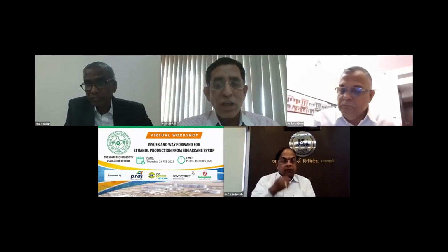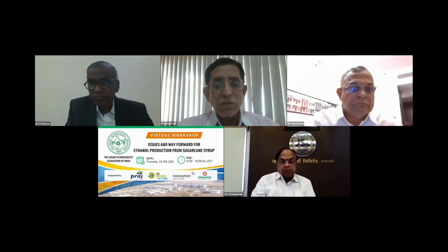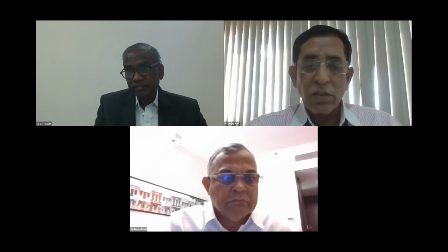Thank you very much. There is one question by Mr. Narendra Rawat. The pH of syrup media of lab culture is increasing. This is probably because of the sterilization. Some nitrogen source is getting degraded, and some ammonium compounds are getting degraded. That may result in increase in pH. How can we reduce or stop corrosion from low pH of absolute alcohol to our plant, as told by you? You have to change the material of construction. For the ethanol evaporation column bottom segment and for the reboiler tubes, we are going for 316 tubes. That probably will reduce the corrosion issue. So this is possible by changing the material of construction.